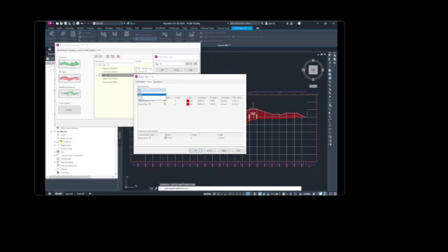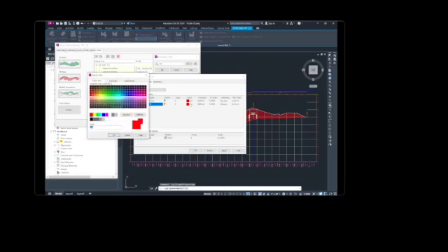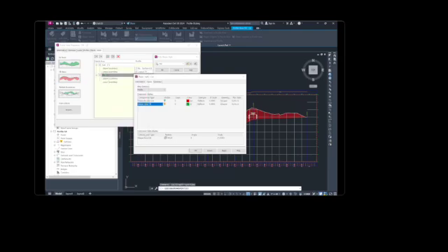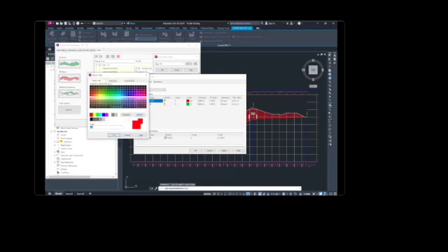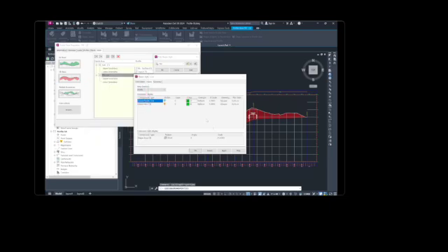And then go to profile view direction profile, and then in the shape area fill, in the color type, click the red color and then change it to 92. So as in the fill borderline, 92.